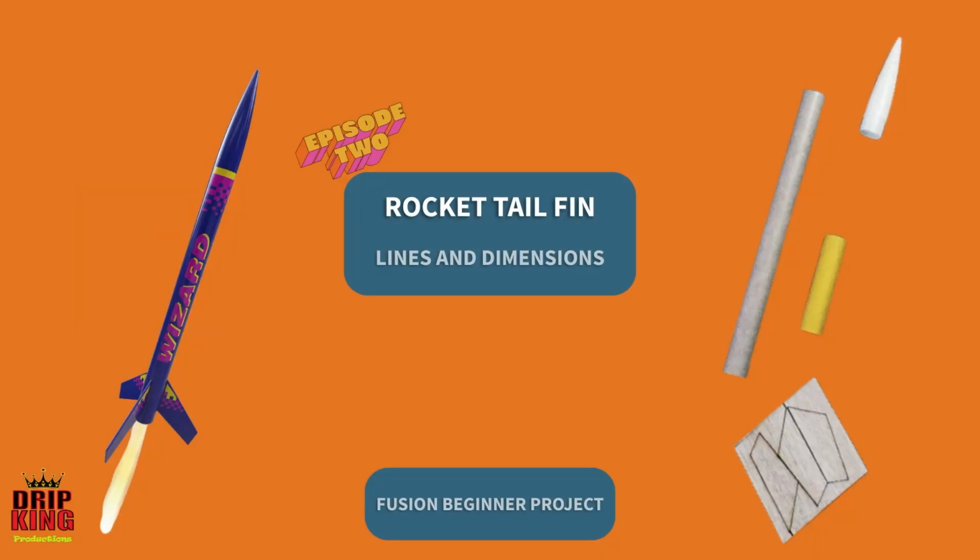In our last episode, we modeled the body tube and inner tube using circles and extrude. Today we design the tail fin. This is where simple lines become controlled geometry. We'll use the line tool, we'll apply dimensions, lock the sketch to fully constrained, and then turn it into a 3D part. No guessing, no dragging, just clean design intent. Let's cook.